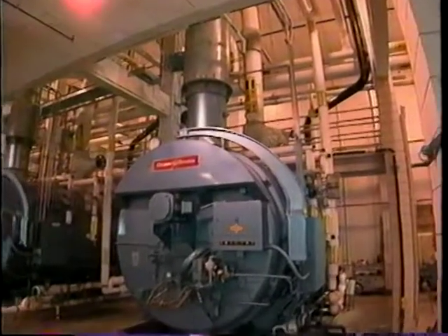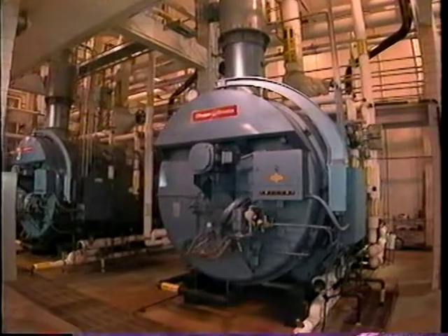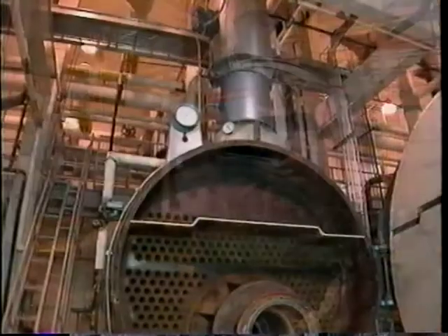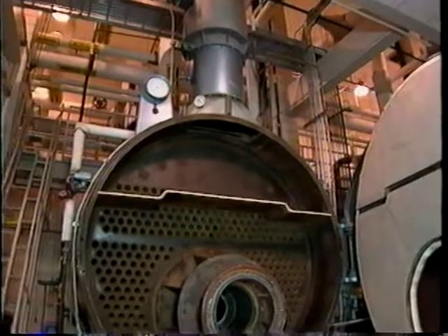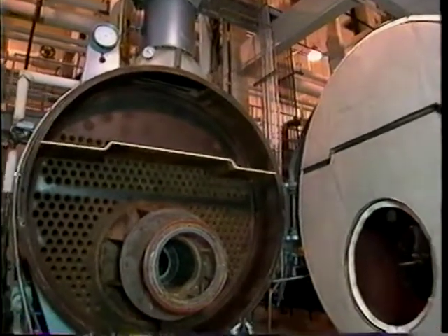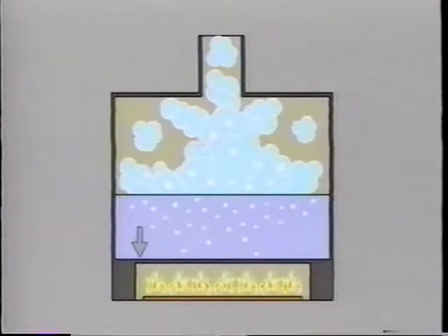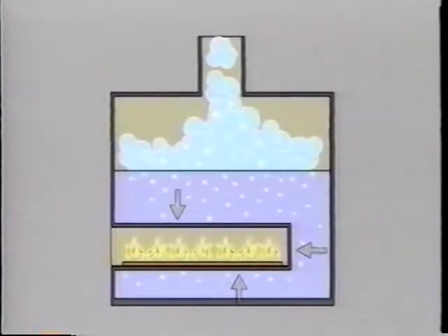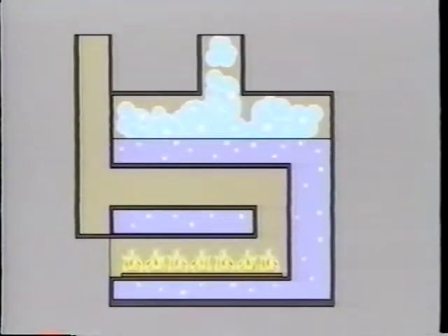Boilers are designed to use heat efficiently to minimize the cost of producing steam. Heating, or thermal efficiency, is accomplished by increasing the heating surface. The heating surface is the part of the boiler where water is on one side and heat on the other. Increasing the heating surface increases the size of the combustion chamber. This allows the fuel to burn more efficiently as the fuel mixes with a greater quantity of air. As boiler designs evolved over the years, greater thermal efficiency was achieved.